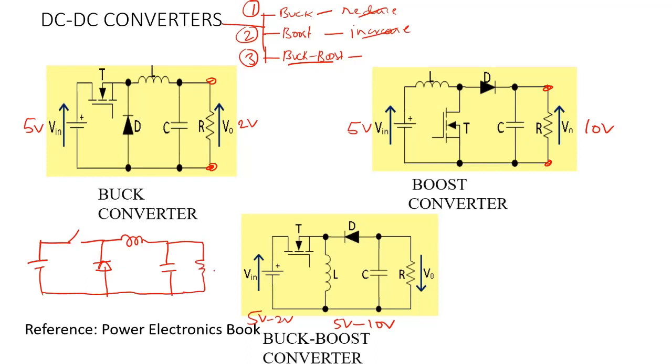I'm talking about the buck converter. So if the switch is open, which part of the circuit? This part of the circuit is not connected at all. The switch is open, right? So that is not connected. If it is not connected, then whatever current has to flow will flow in this circuit. An inductor is a type of element that stores energy in the form of a magnetic field. So whatever energy is stored in this goes and circulates via the diode to the load, which is a resistor, and comes over here. What happens if the switch is closed?